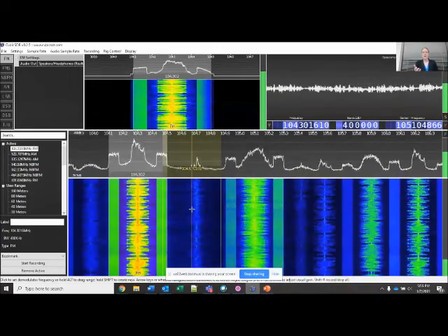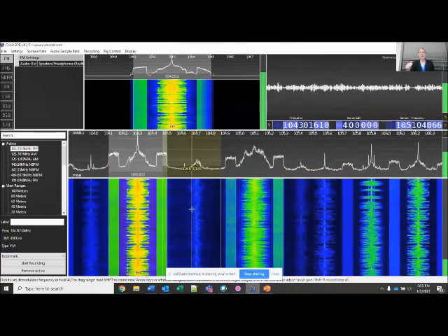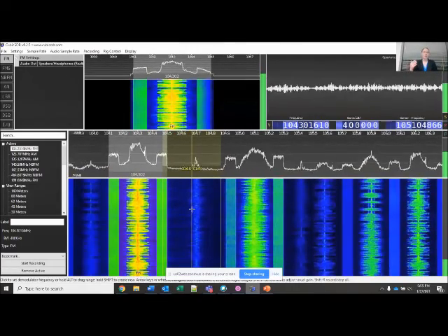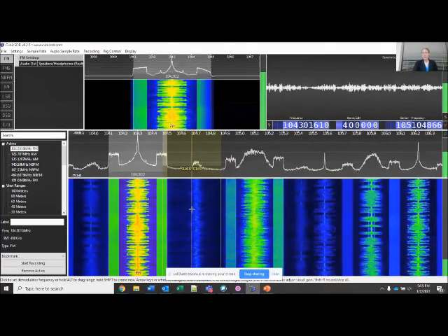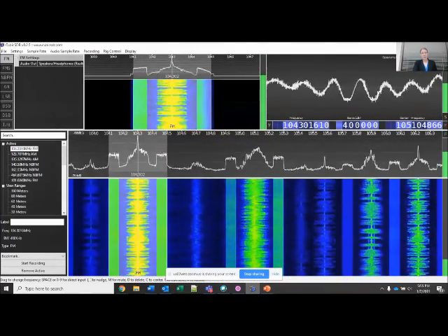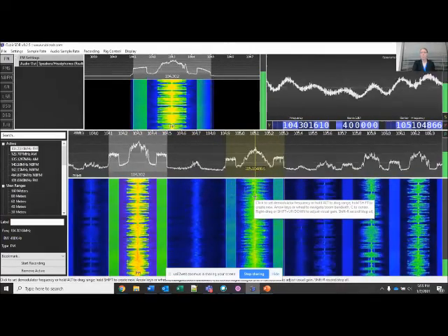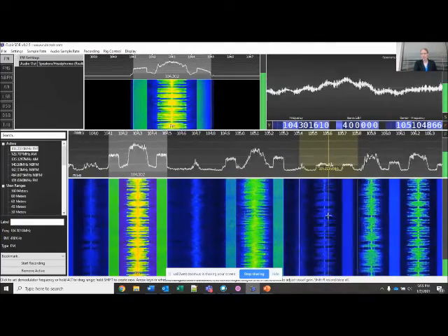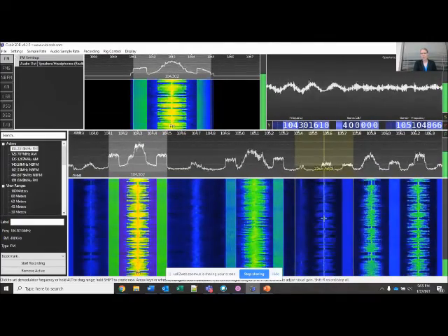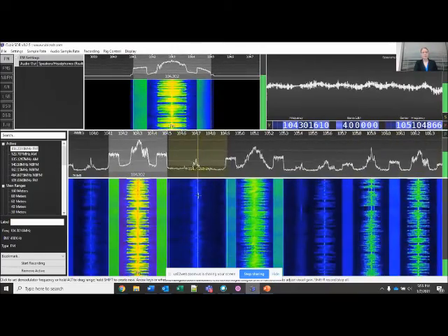I would never try and take a plot like this or a spectrum like this and compare it to an FCC limit or a CISPR 25 limit. That's really not what it's for. But it does really nicely show me that this station here, 104.3, is coming in a lot stronger than 105.1. And there might be kind of a ghost station far away over here at 105.5. There's some weaker stations over here.